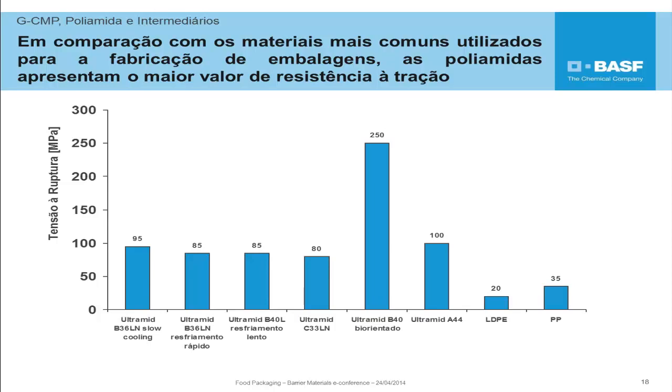Slide 18. As you could see in the previous slides, the great difference of the polyamides is in the property of its molecules. We see that the majority of semi-crystalline materials are very similar when the temperature is well above the melting temperature. All these materials are in an amorphous state, but when they begin to be cooled, they begin to have some differences. Part remains amorphous,